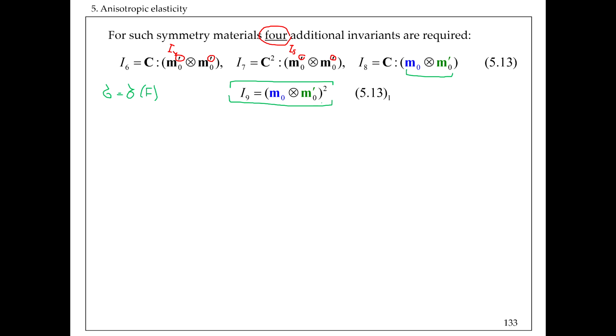So that's how we derive the responses in terms of stresses. And very similar to the tensors that we already considered, to the vector M0 tag, when we apply the deformation gradient F on that vector M0 tag, basically that's a transformation of that vector into the deformed configuration.